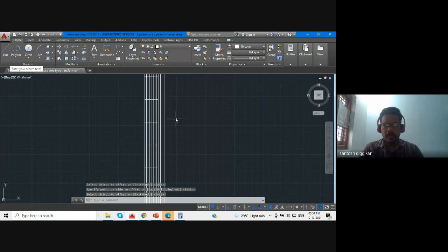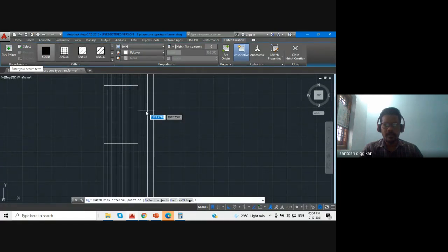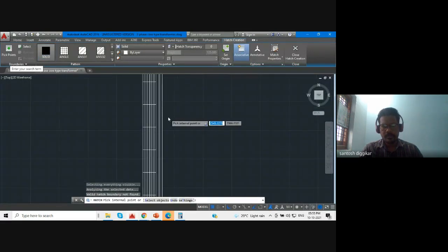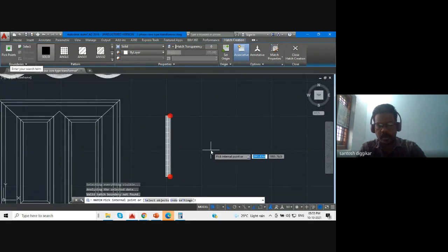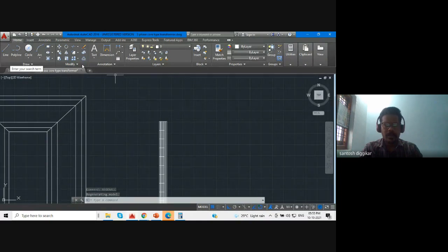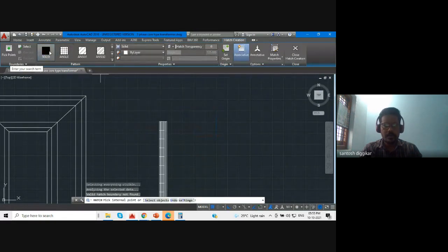Okay, so this is LV winding. Now you can see this is what in between layers. These are the four conductors. If you want to hatch the parts, let's see, solid. Okay, closed path is now showing. If red dots are coming, type REGEN. Regen all. Hatching is not doing properly. You can go to hatching, go to option, and set this to maximum tolerance. Let's see at this time whether hatching will be done or not.